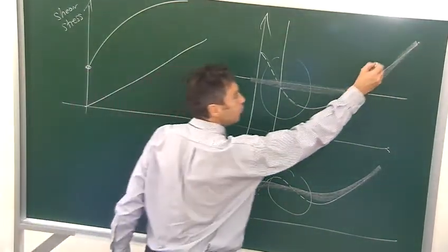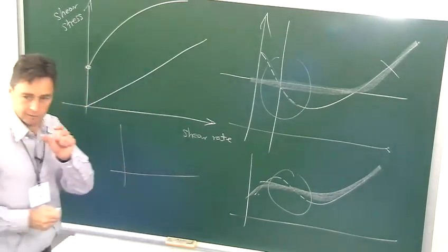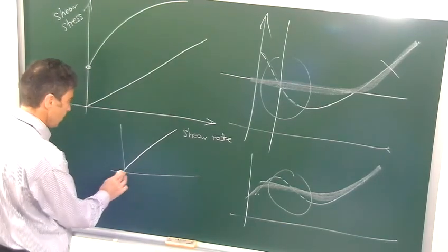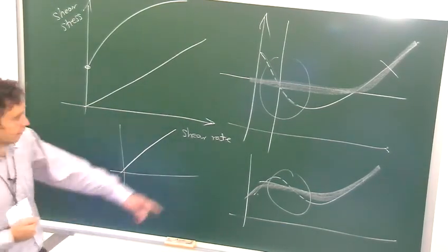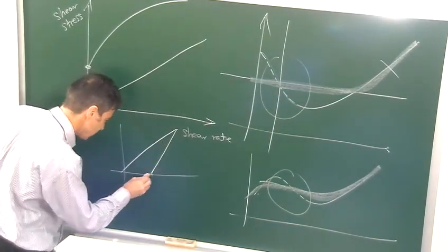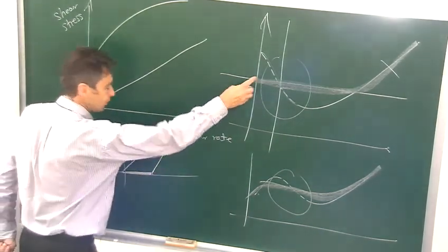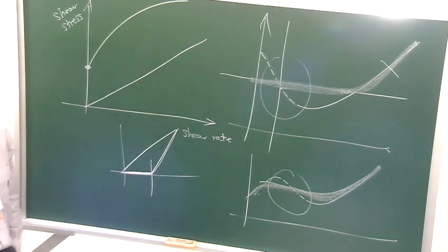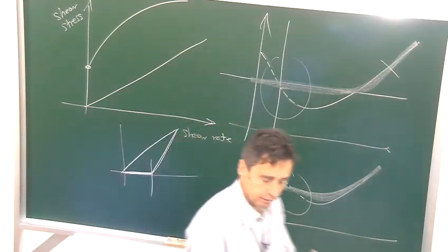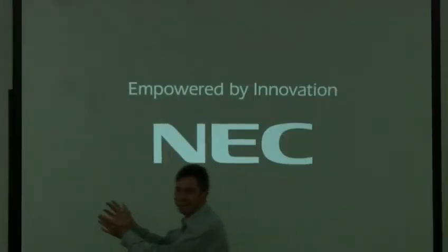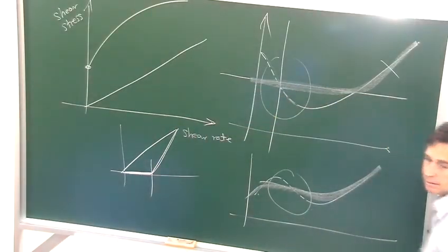So in this branch up there, because it's a very small device, you find that the velocity profile is a simple shear up here, but over these kinds of regimes, what happens is that it breaks up and you get regimes where part of the material, in this case, for example, is not moving at all, and another part of the material is moving. So you've got this shear band here. So what's happened is that the material has been intrinsically unstable, and it's become spatially inhomogeneous in order to counter the fact that you've been trying to set conditions that would otherwise make it unstable.